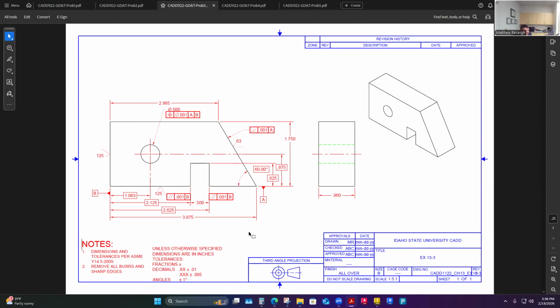So then I established datum B, right? Oh yeah, back left side surface is going to be datum B. And it looks like I've only established two datums on this. Yeah, so A and B. With B, I'm pulling a lot of locational dimensions, looks like, for the slotted feature of size. And A and C, or A and B both, I'm pulling locations for a feature of size on the whole. And I'm even controlling some other surfaces from a datum.